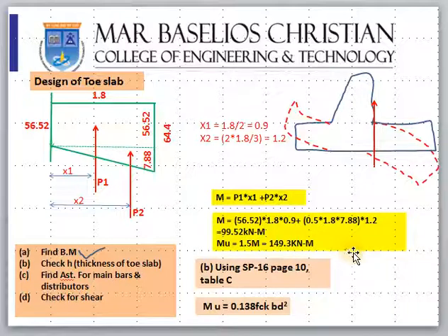kilonewton meter. So once you have got the bending moment here, then our aim is to check whether the thickness you have provided here for the heel slab is sufficient to take this bending moment. That is a check, next check. So it's the same as that.